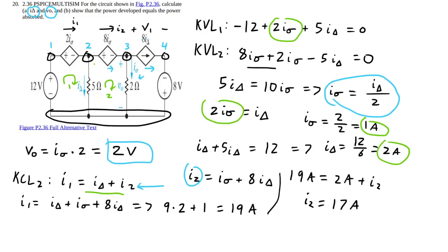We're going to consider this third loop. We want to find the voltages, and we have the currents and the voltages so we can calculate the drop. So let's go ahead and do our V1 as a drop because the current's going through it in our little loop. And we have a gain of 8 volts going from minus to plus, since there's a voltage source.